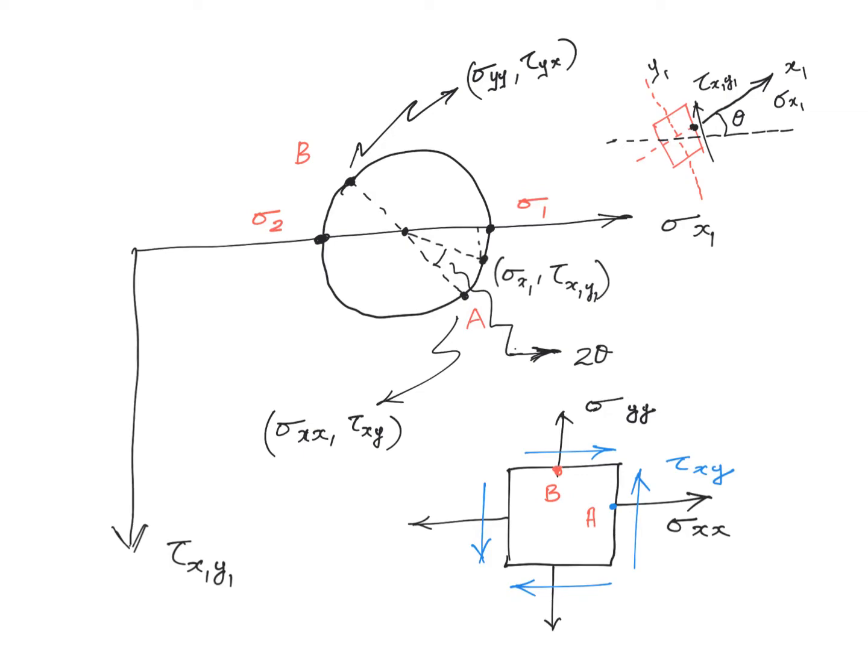Now coming back to Mohr circle, the first thing you should remember about Mohr circle is the axis or the sign convention. What I like to do is I follow the sign conventions as specified in the book of Timoshenko. So I have my tau x1 y1 axis coming down and sigma x1 axis going towards the right. Key thing is, see this, I'm plotting tau x1 y1 here. I'm not plotting tau y1 x1, because what happens is